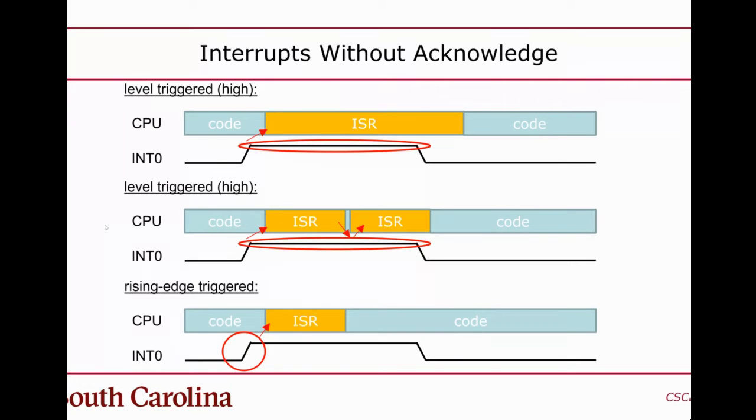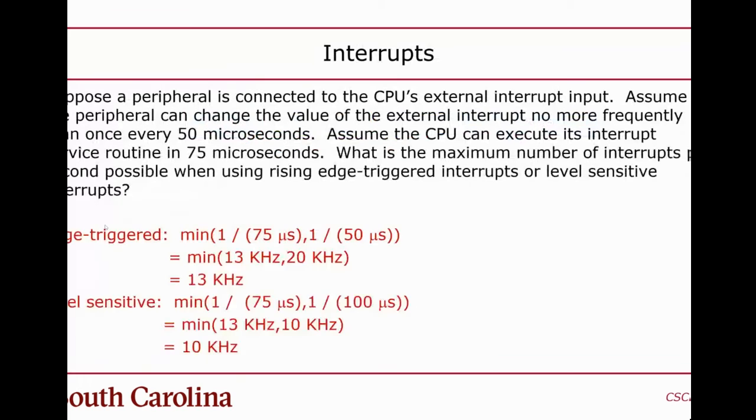And also, by the way, interrupts are events that happen, right? They're typically events, like a packet's received or someone hits a key on the keyboard. So if the level of the interrupt wire is high too long, it would cause, for example, a key to be registered twice. With edge triggered, it's a little bit harder for that to happen because you're looking for edges. It's an edge there that's causing the CPU to enter the service handler for the interrupt. So it's harder for you to have kind of a false alarm with edge triggered.